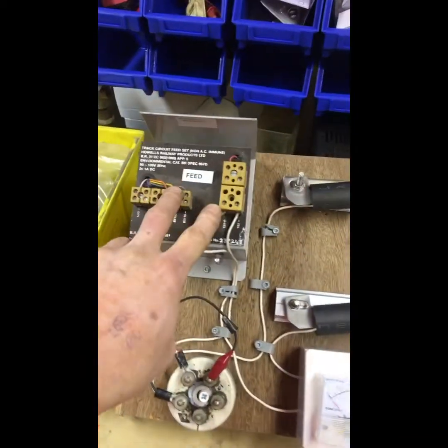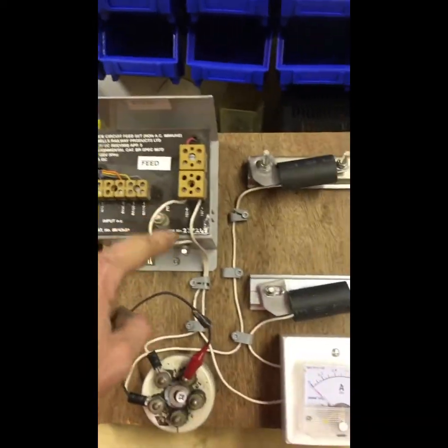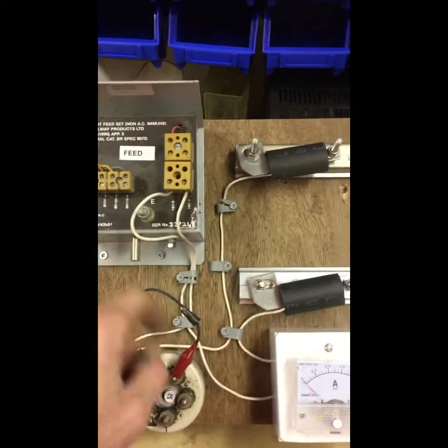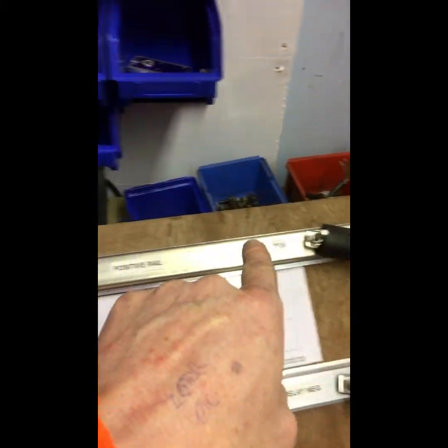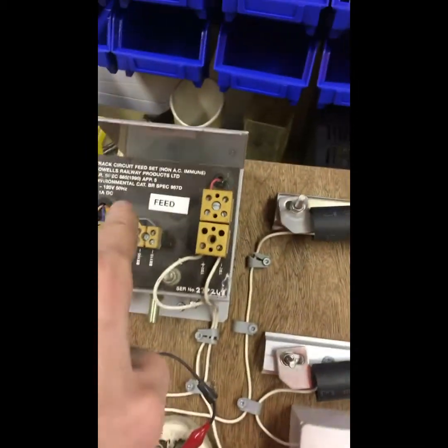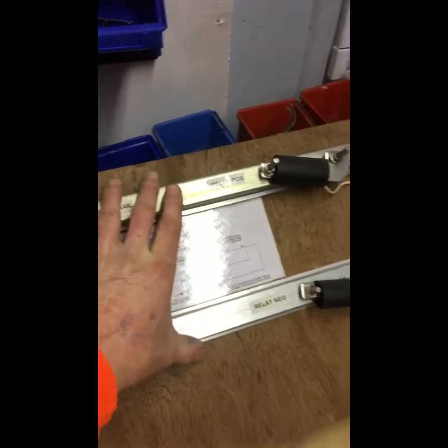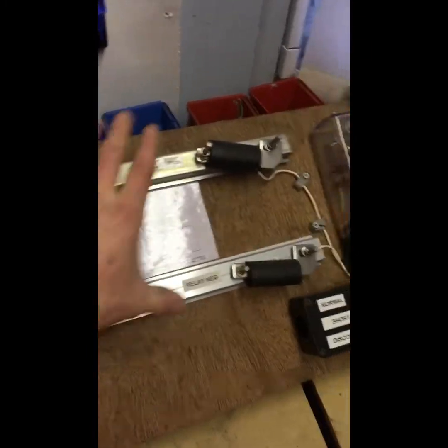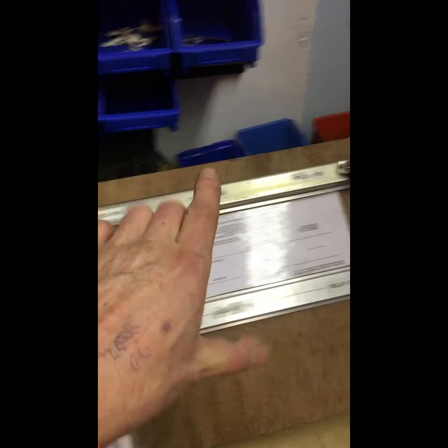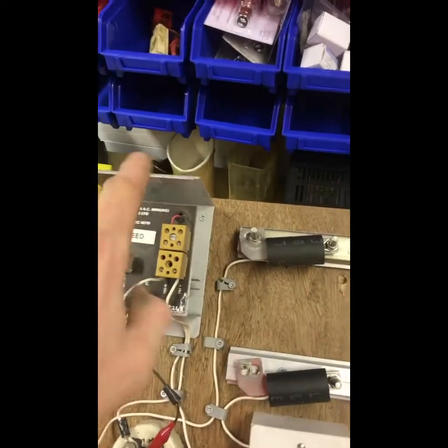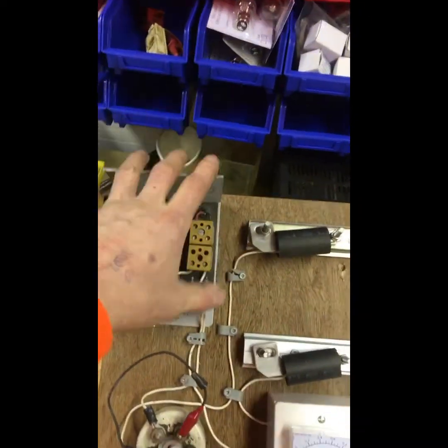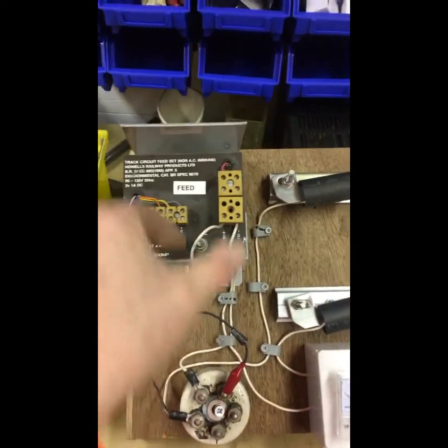If you consider this is our test setup, it's not powered up at the moment, but we have our feed supply. Now our positive feed supply, in this case here, goes down to our track, round to our relay, returns down the other rail, and would go back to our power supply. If we were to put a train on here, this would act as a short circuit, and yes, it would stop the current coming from the supply from reaching the relay. That current would then be shunted back round to the power supply. However, it being a short circuit, it would likely damage the power supply, or at the very least blow the internal fuses, the inline fuses.